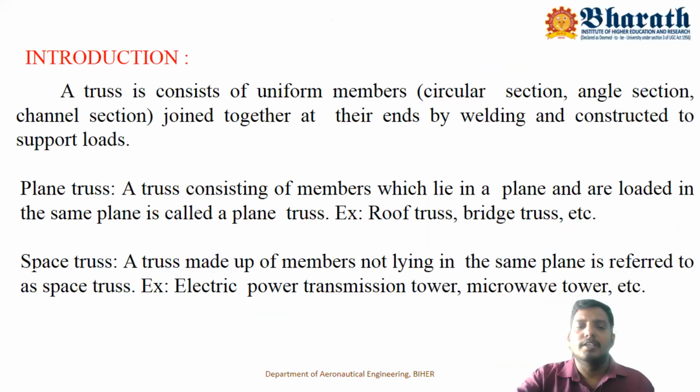So, what is meant by truss? Truss is nothing but a group of structural members connected or welded together to carry axial loads. It is generally classified into two categories: one is plane truss, and the other is space truss. If the truss consists of members lying in the same plane or loaded in the same plane, then it is called a plane truss. Examples: roof trusses, bridge trusses, etc.